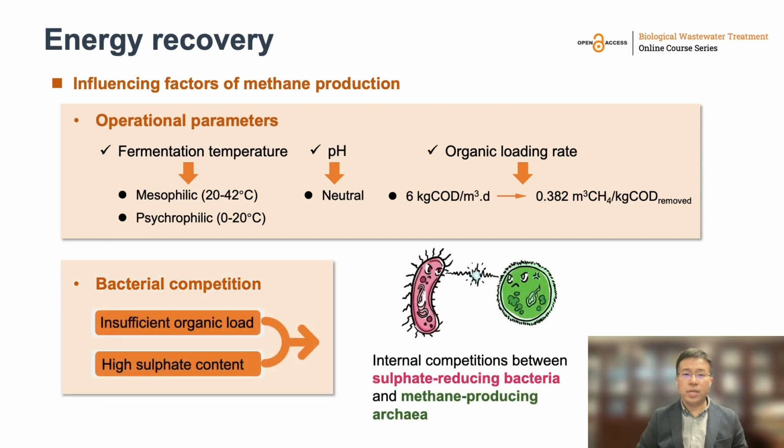As for the bacterial competition, it can also affect methane production. For example, if the organic load is insufficient and the sulfate content is high, the methane production will be affected due to the internal competition between sulfate-reducing bacteria and methane-producing archaea for organic substances.